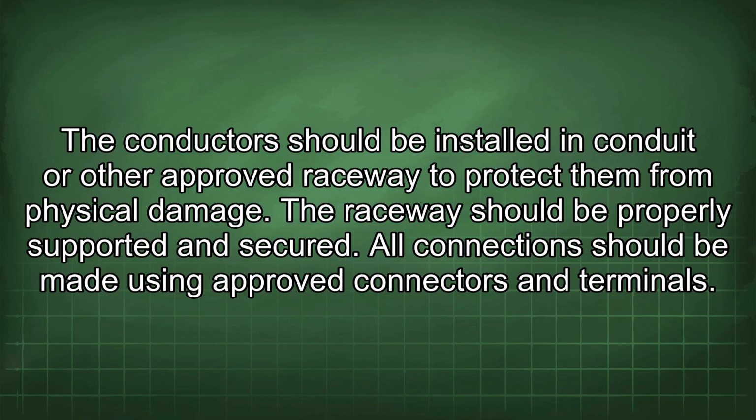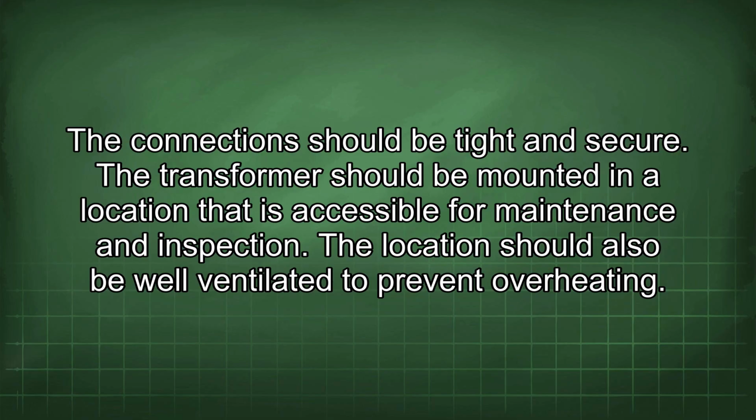The raceway should be properly supported and secured. All connections should be made using approved connectors and terminals. The connection should be tight and secure.